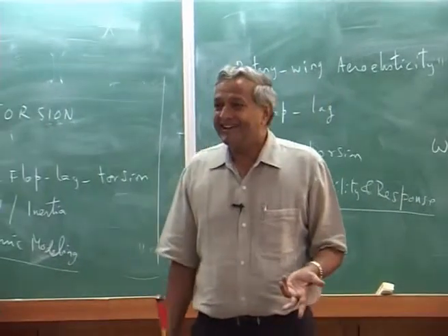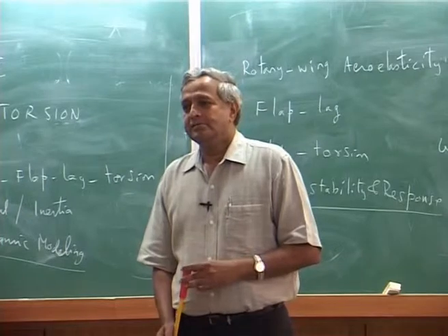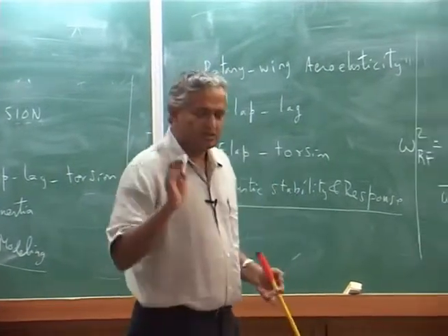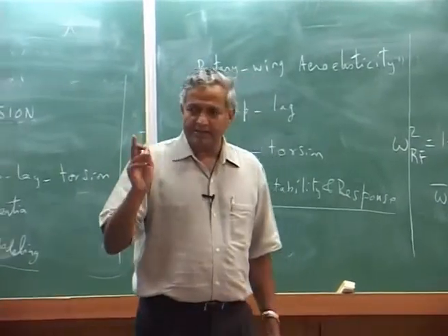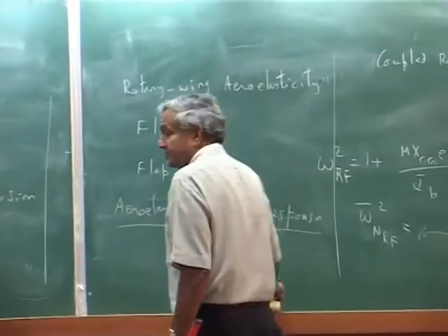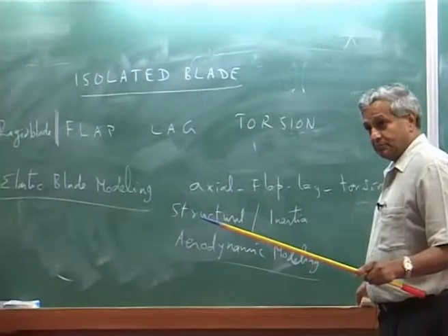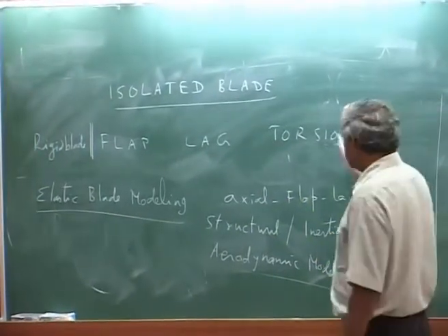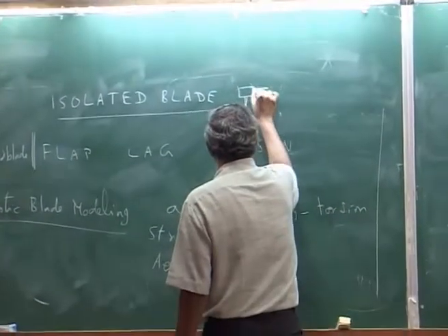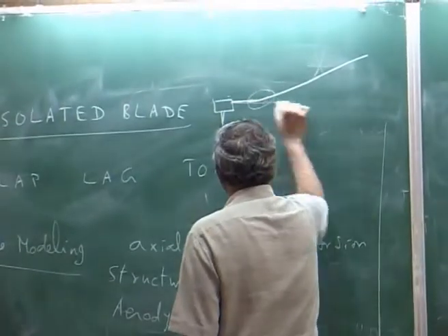My question was, is the hinge going to take most of the bending which is going to happen, or the blade is going to bend a bit? Not the blade, hinge. Please understand, your question, blade also will bend, but it is in a second mode, third mode. First mode, majority of the deformation, if you say this is the half bar, majority of the deformation will happen like this. This is the first mode.